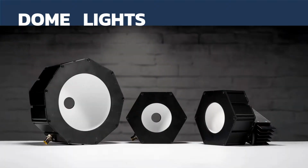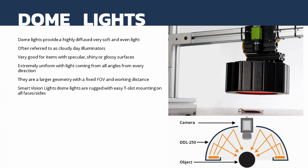Moving on to the next form factor, we're going to talk about dome lights. And you can see from the diagram here on the right that a dome light is just what it sounds. It's a dome, a half dome, if you will, with a hole in the middle for the camera to project through, and they're lit from the outside ring of that dome. So there's actually a ring light facing upside down in there, so it's facing upwards in the dome. All the light that comes out of the dome and onto your object has been reflected off that curved surface, which is also coated white with optical matting, as you can see inside there.